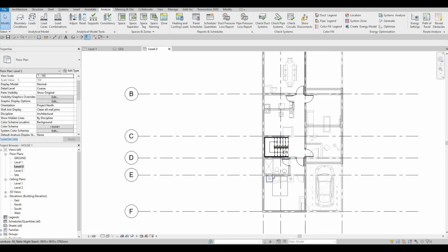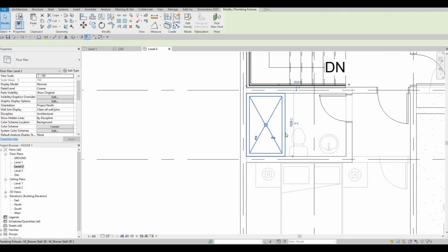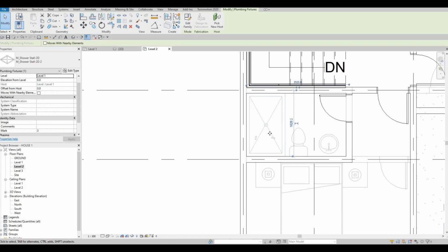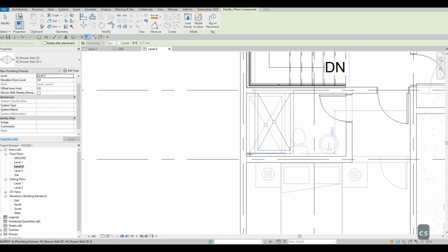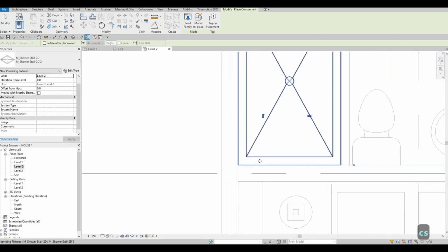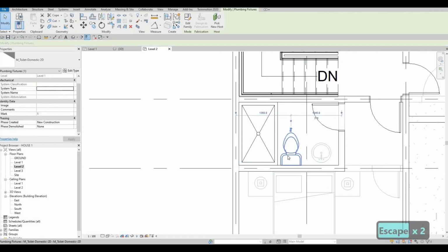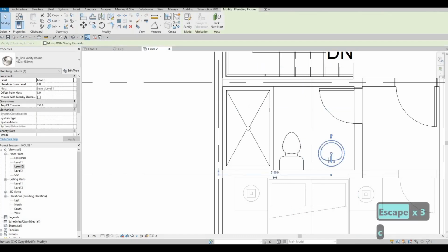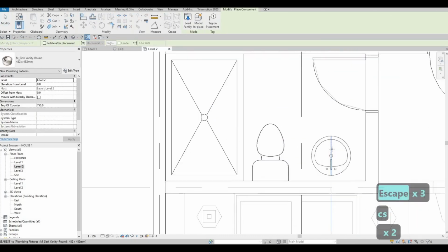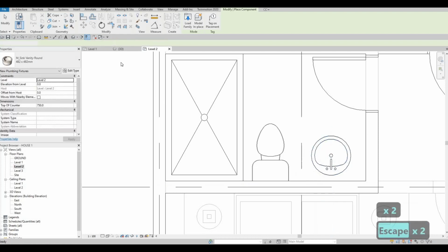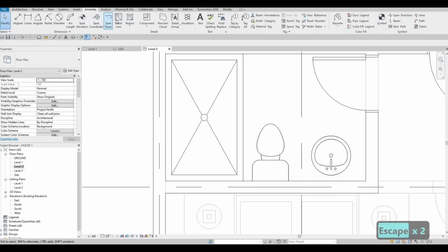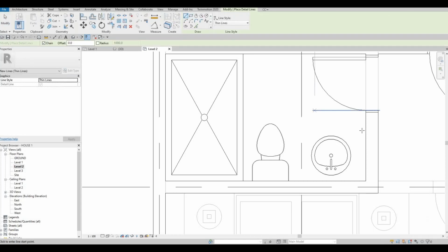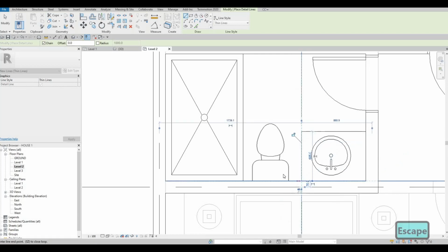So now, what I'm gonna do is, I'm going to grab this. This is from below, so I could just CS that, and then add it straightly from there as well, because it's basically the same thing. Add there, select that, CS, spacebar to change orientation, and the only thing that we cannot select is the detailed line. Let's just add a thin detailed line for the sink top.